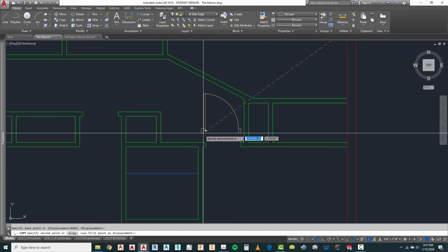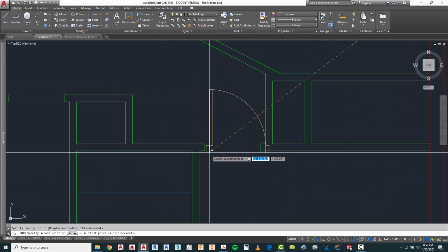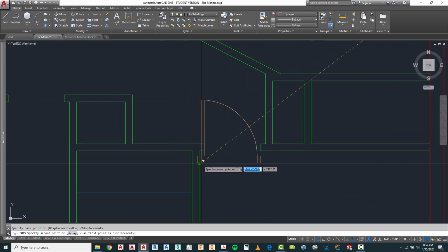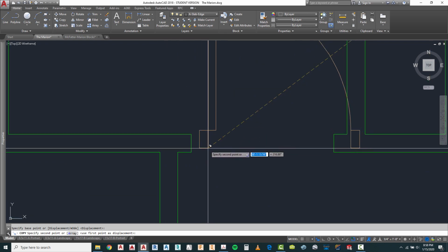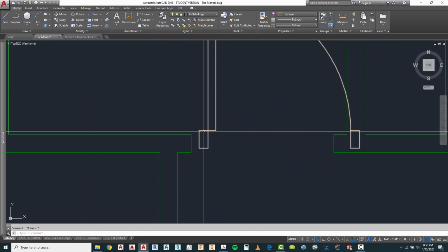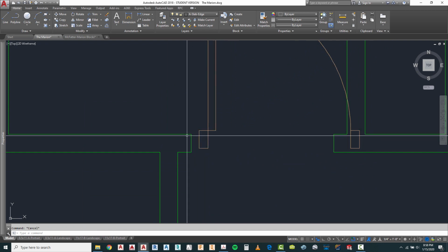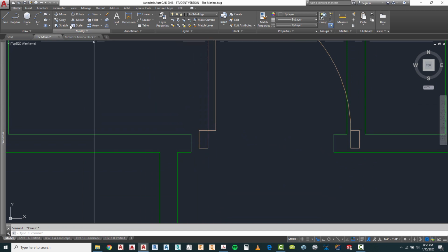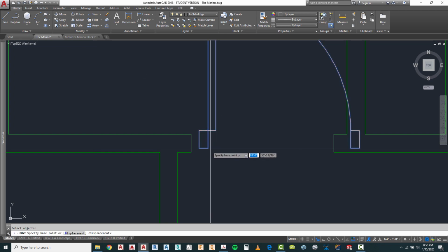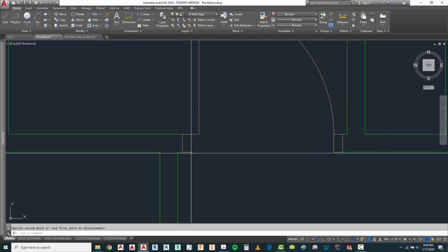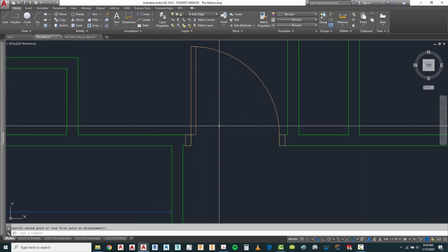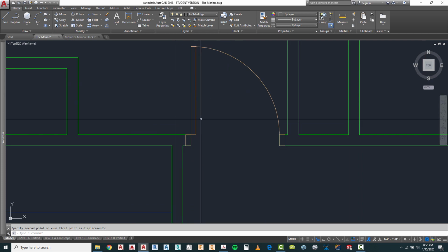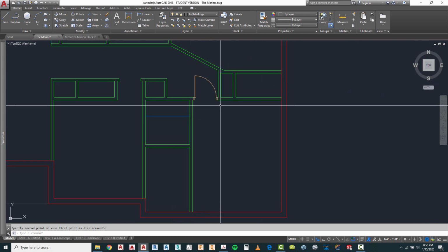Now these doors that we're placing in here are being placed inside of a frame wall. These are stud frame walls. So the jambs of the doors, which are these things located in here, are going to end up within the wall itself. I'm going to move this door right to here, and as you can see, it's located within the walls. The unfortunate thing though is that it's facing the incorrect way. I want it to swing in this direction.